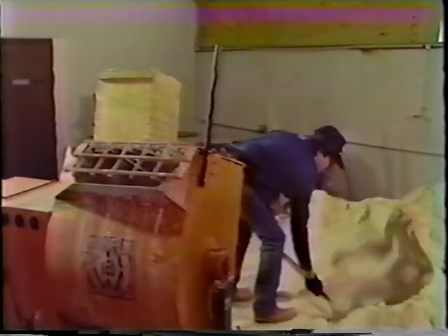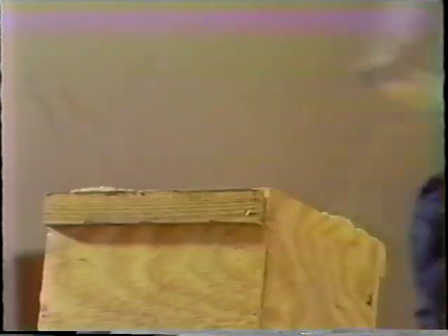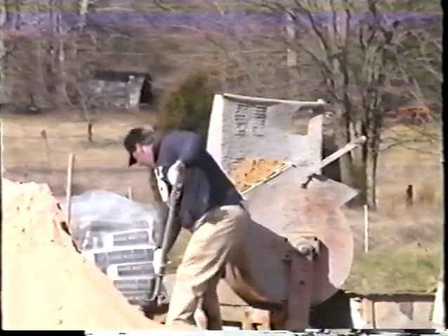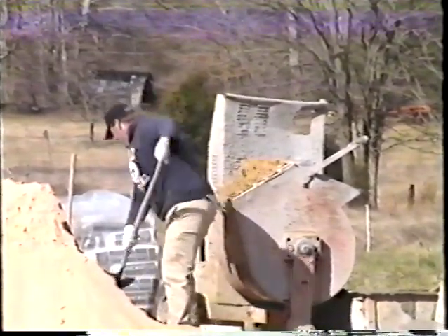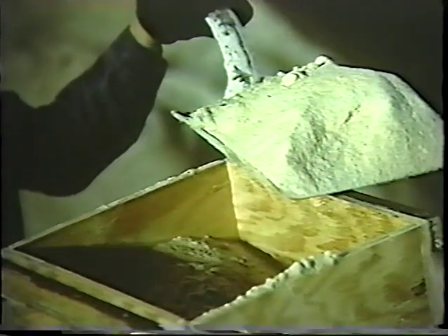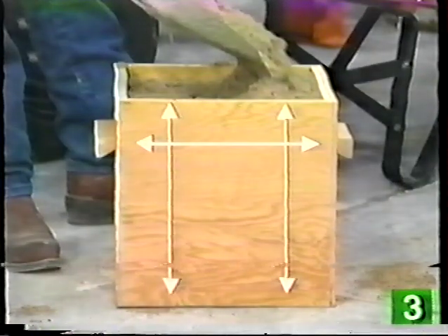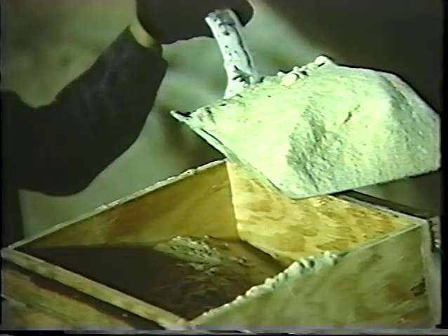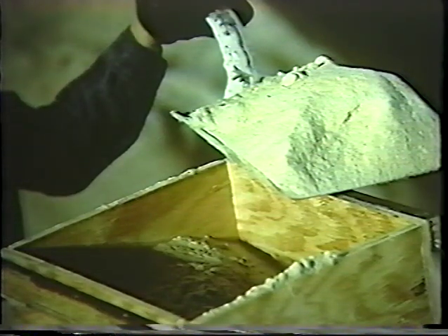The amount of sand used in mortar is also very important. If too little sand is used, shrinkage will be a problem. Too much sand reduces strength and lowers durability. The amount of sand that you can measure with a shovel is usually inaccurate due to the differing sizes of shovels and the inconsistent amount of sand that is picked up each time. A container like this 1 cubic foot box is preferred. It can be used to accurately measure the sand being added to the mixer. You could also count how many shovels it will take to fill the box. That's also acceptable. However, you must check this count daily because of changing moisture conditions.